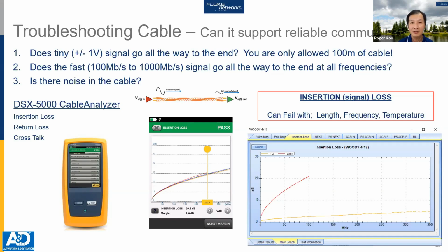I would like to briefly introduce some of the other parameters that the tester checks, such as this first one, insertion loss. Now, what is insertion loss? Basically, you send a very low voltage signal, 1 volt, and it's supposed to go a distance of about 100 meters. At the end of this cable, you determine how much of this power you still receive. So that's called insertion loss.